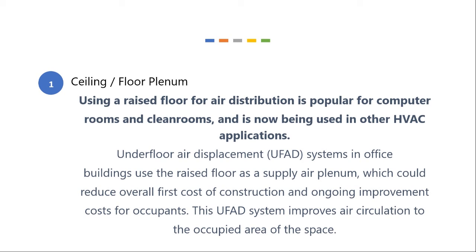The other option you can use as a plenum is the floor. This is really popular, especially in clean rooms and server rooms. It's called an underfloor air displacement system. The floor is raised, and that reduces construction costs and improves system efficiency.